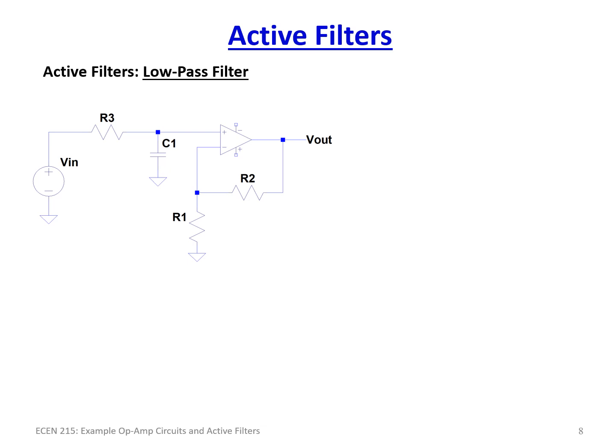So here is just a simple low pass filter. Obviously, you've seen this before. This is just a resistor capacitor filter like you've seen in the previous lecture on frequency response. The only thing that we've done differently is we have put a non-inverting amplifier on the output stage. The advantage of this is no matter what type of load we stick out here, it is isolated from this filter. So we're not affecting the current draw and the output stage of the filter based upon the load.